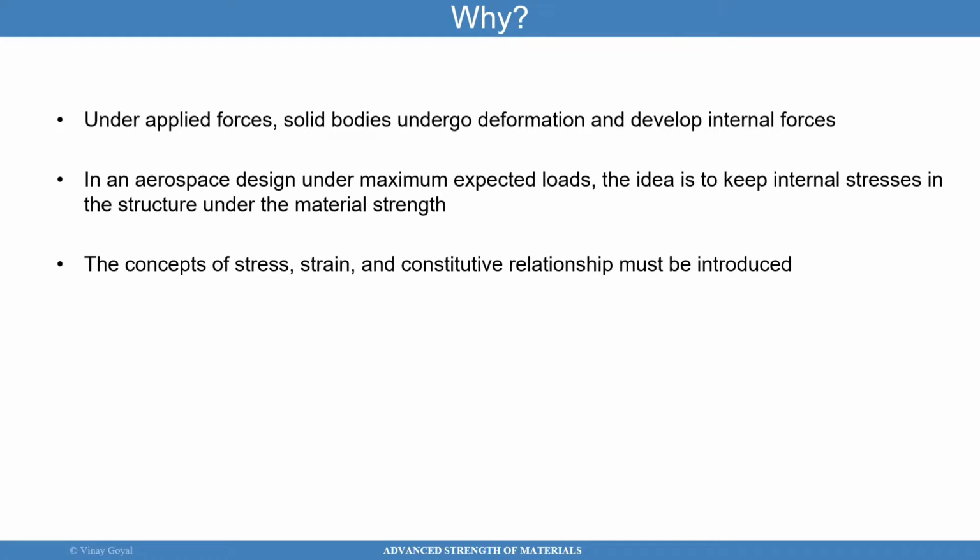And when you apply forces to an airplane or rocket or a car, there will be internal forces acting in the vehicle that are reacting the external loads that are being applied. But there's a location in the structure that's going to be a weak point because the stress will be too high. And that could be the location where it fails.